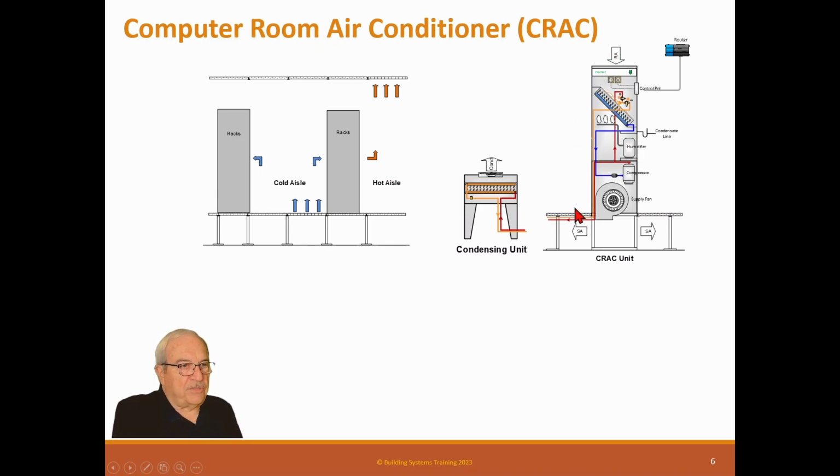These units are normally about 5 or 6 foot tall, so not terribly tall, and you've got space up here. But the way I prefer to do it is, if we've got a return air plenum above the space, I like to put a perf grill right here and let this hot air drift up, which it naturally does because heat rises, up to this grill. Then I take a duct from this up to the ceiling, and I put this under negative pressure. So all of these units are sucking air out of this plenum area, and it's sucking it out of the hot aisle. So we don't allow the hot and cold air to mix, because there'll be a cold aisle over here and a cold aisle over here, then a hot aisle. So this segregates the air very well. It works really good.